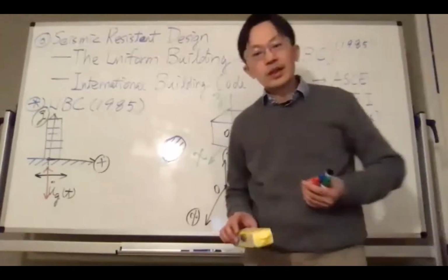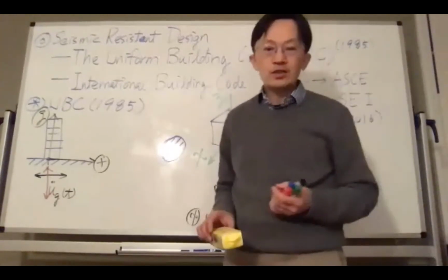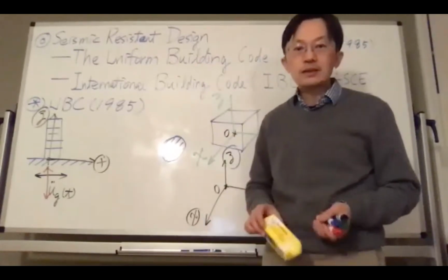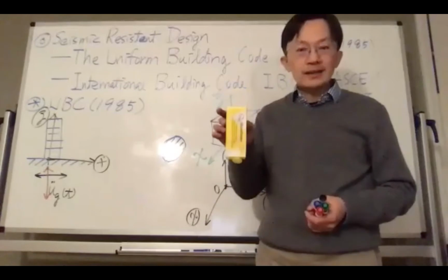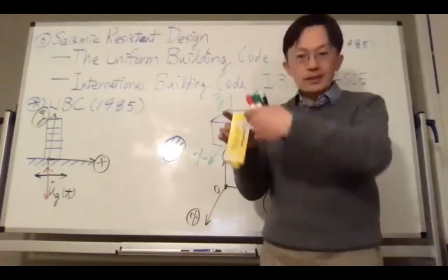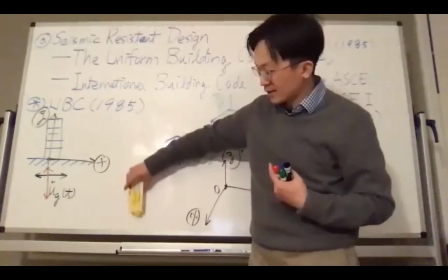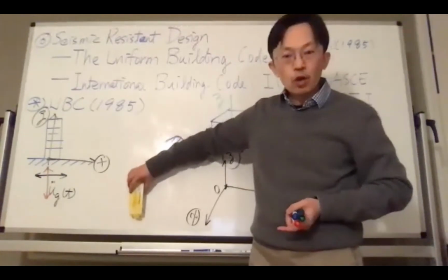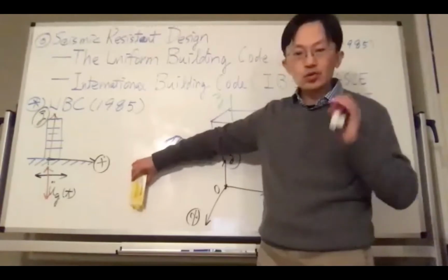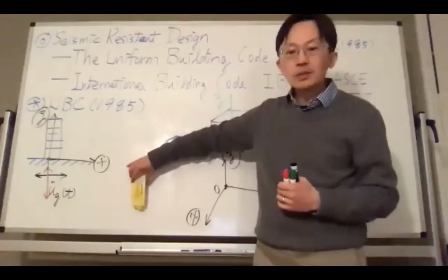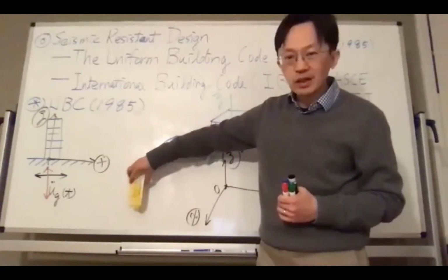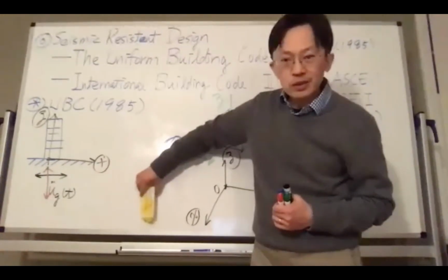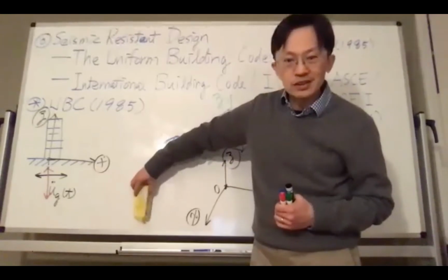And so what's the answer? The answer is case two. Case two is more devastating to this structure. The reason is that the strong axis for this building is the vertical axis. Assuming the same overturning moment, it is more difficult to turn this building in this direction, but relatively easier to turn it if you shake like this. Just imagine this kind of overturning.